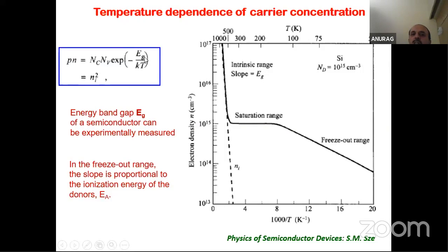So this is the kind of relationship which is followed by a semiconductor. If I do Hall effect measurement, suppose for an N-type semiconductor, silicon for example, 10 to the power 15 per centimeter cube, what you see here is over the entire temperature range, from 50 Kelvin. You don't need a liquid helium kind of cryostat, but if it goes up to 50, that's better. It's not 4 Kelvin or something that is required. So 50 Kelvin to, let us say, higher temperature.